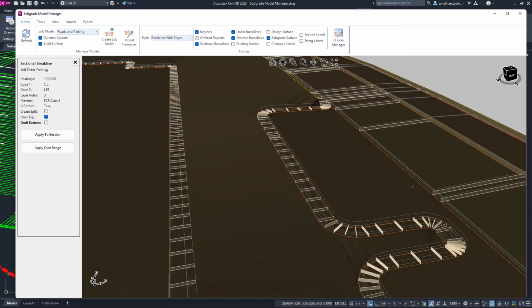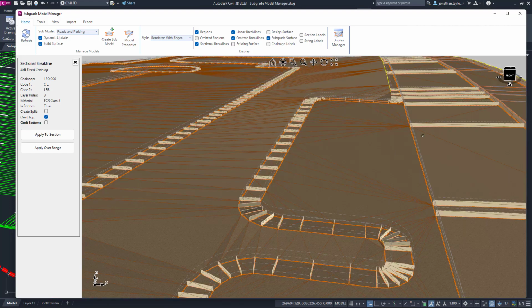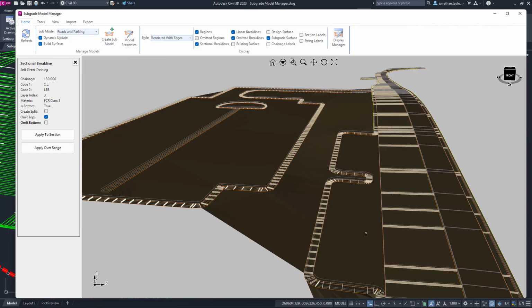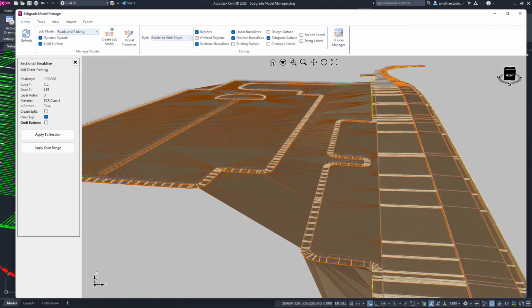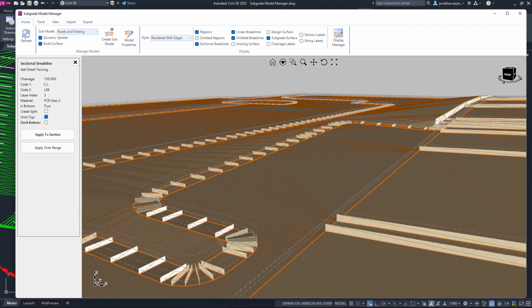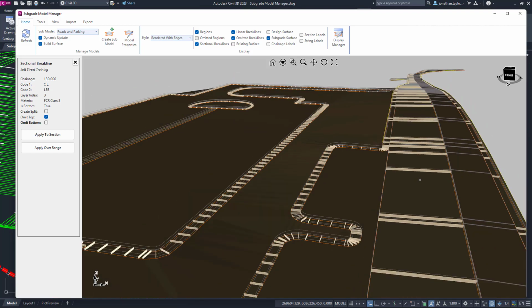The same goes with the car parking bay, which is parallel here to the road. We've used Model Builder here to trim the sections of the car park out, so this is why you can only see the edge of bitumen. Then what's happening is that the software is triangulating between the curb subgrade on the design to the bottom layer automatically. So it's always looking for the bottom layer of each of your strings and simply trying to connect them together.